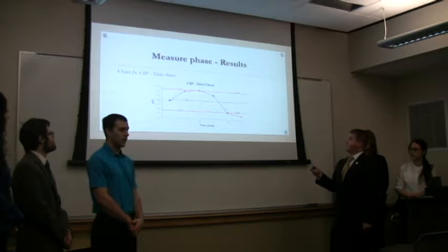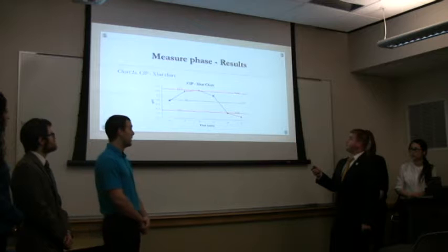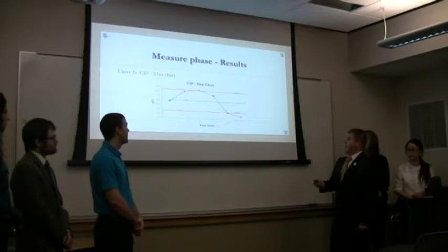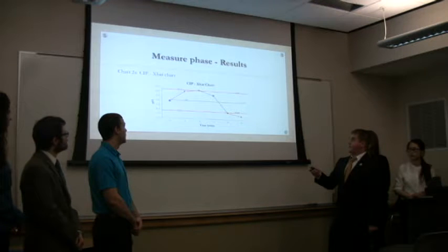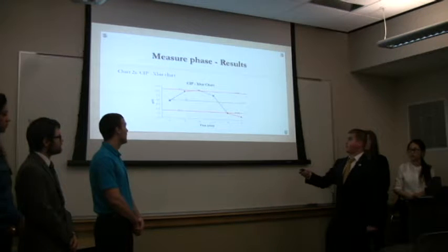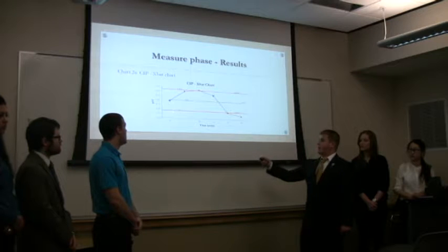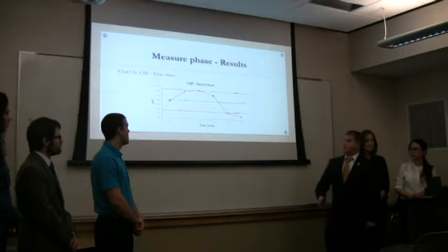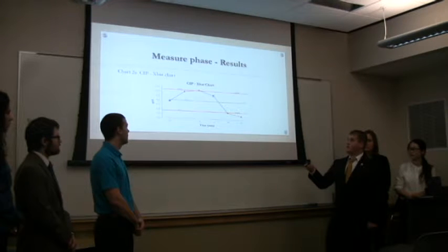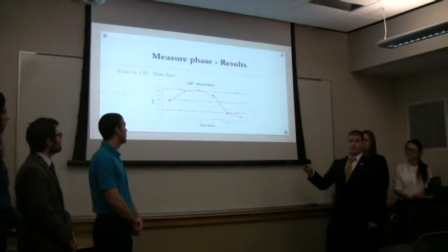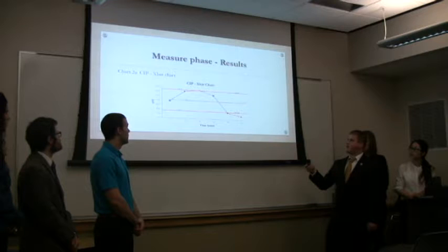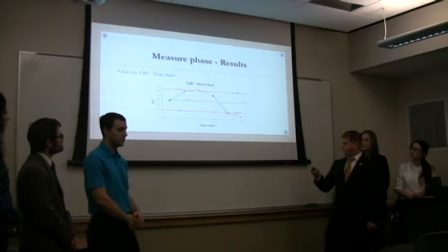So in this particular case, the upper limit ended up being about 10 pH, maybe 10 and a half, and the lower being about 8. And the actual moving line is the data plots for each given time increment. So right as we started, 5 minutes, 10 minutes, et cetera. The biggest thing I want you to notice about this chart is that, once again, we hit right around 9, and then as the neutralizer is added to the CIP systems to wash, it starts jumping up a little bit above what we would consider in control.